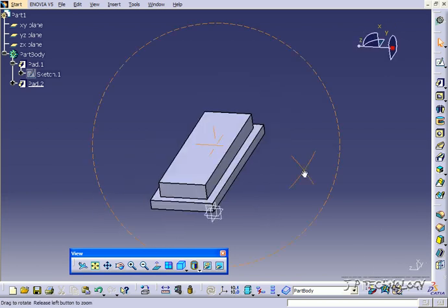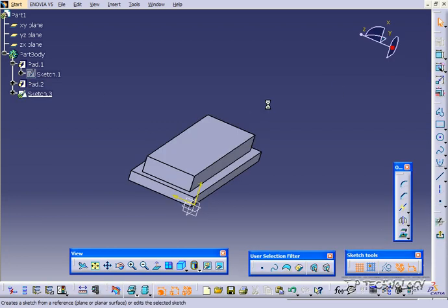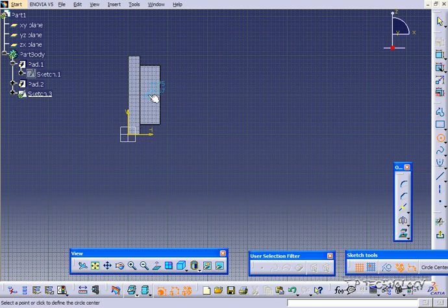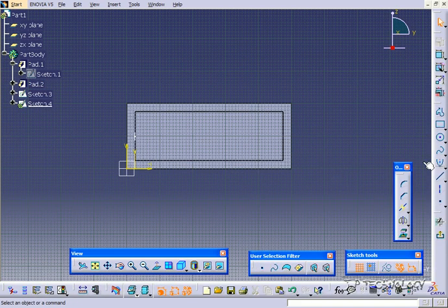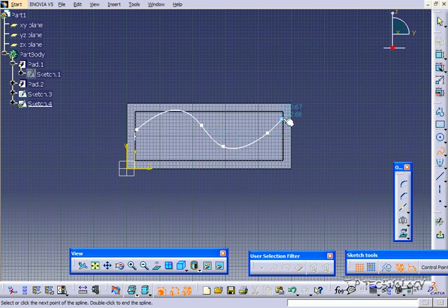and this time let's create one that isn't a square. So let's do a circle like we did on the last one. So let's click this face, click sketch, and we'll click circle. Just draw a little circle in there, and we'll go back, click the top face here, click sketch, and as we're going to be able to cut through this, we can make a route for it to follow. So if we use the spline tool, you can make a little path and a little route, and everything's going to follow and cut right through it.